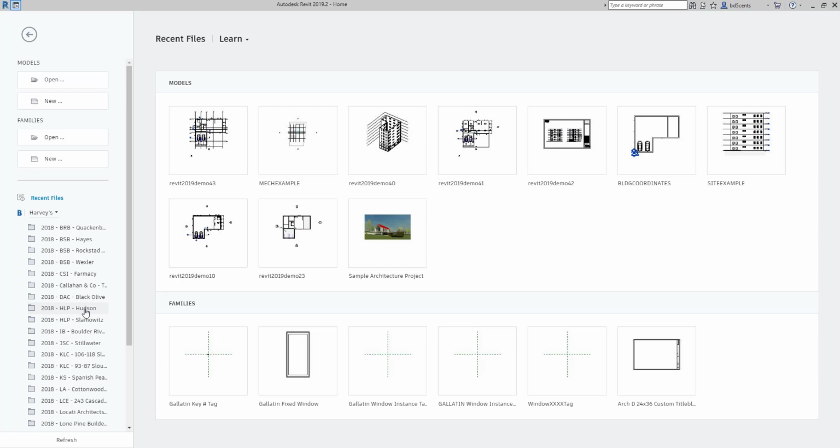In class, I've referenced that general Revit templates can be about 40 megabytes. Anything higher than that's a bit excessive, and anything lower than that is probably not a well-developed template. So for this lecture, we're going to discuss how you can reduce the file size when project stakeholders are bringing in too many items that kind of fog up that project.